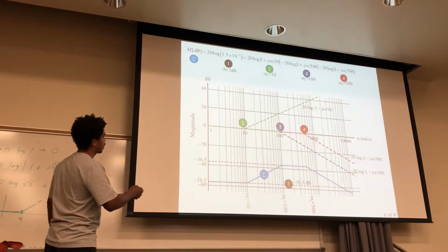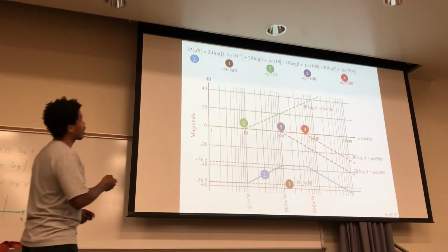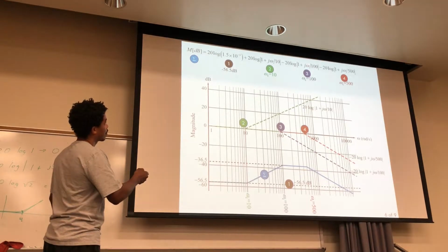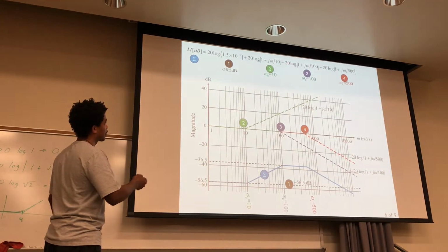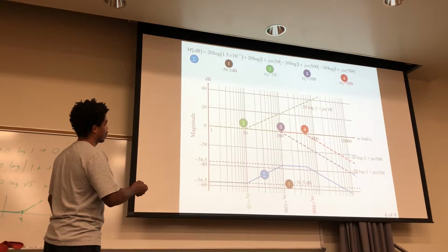Okay, and then that's why, when it gets really small, it asymptotes to 0. And the same thing happens to 3. So for 3, it had a cutoff frequency of 100, right? So if I put 100 there, that's going to be 1. And that means it is minus there, so it's going to be like minus 3 decibels. So it's going to be just a little bit below this 0 point. But that's like the true curve, right?